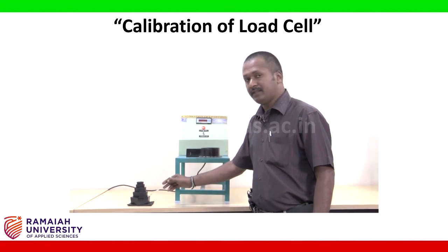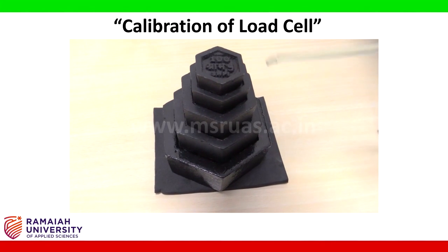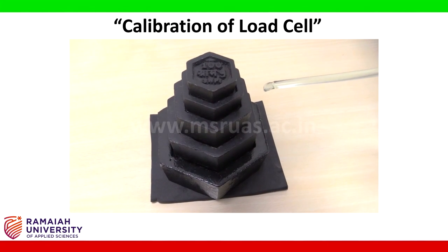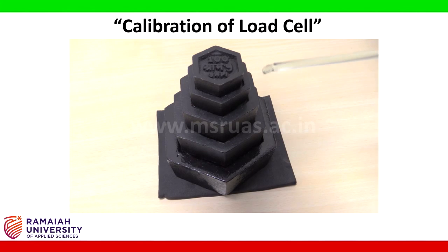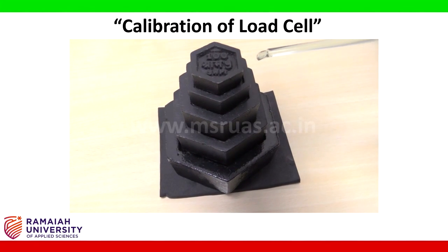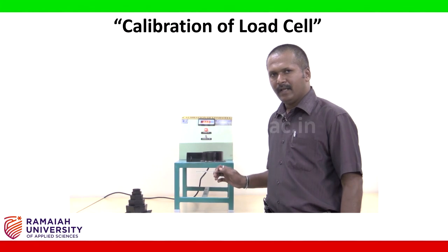And standard weights: you use the standard weights on this strain gauge arrangement to measure the actual load versus the indicated load, and to find out the percentage error. Now let us start the experiment.